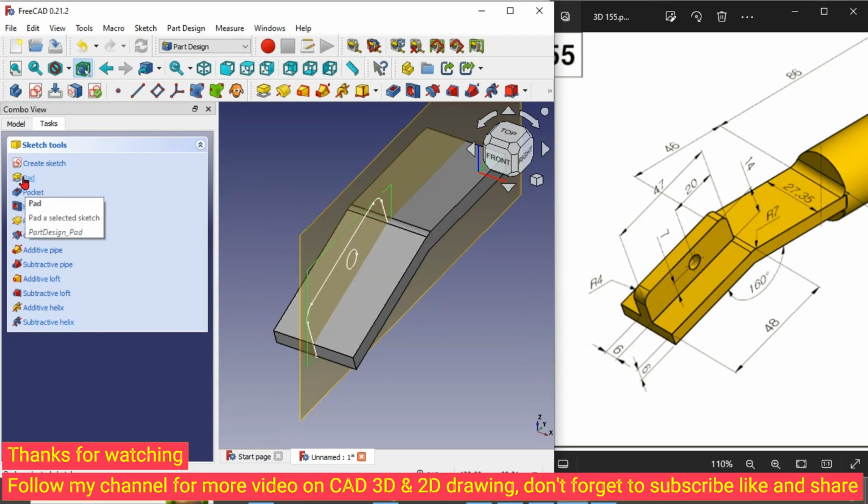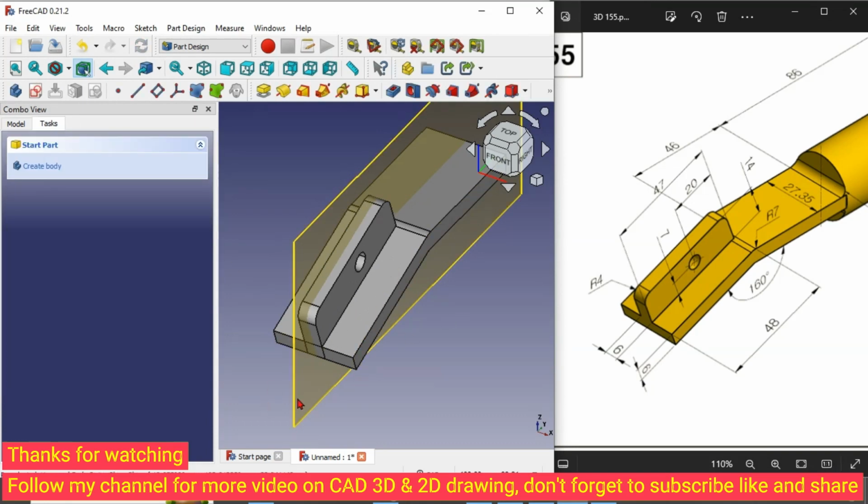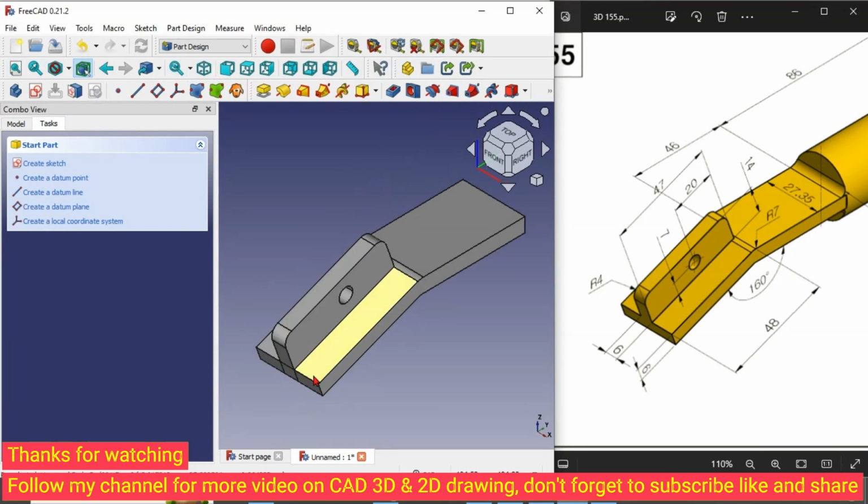Now we give it a pad. Dimension is 6, but I want it to be symmetric to the plane because we placed the drawing in the middle of this block. So we click symmetry to plane. Then okay, click on this sketch, click spacebar to hide it. Okay, done for this side.